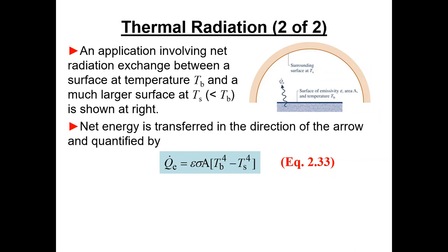They don't have to talk about it, because view factors get complicated. You have to do the three-dimensional geometric integrals in order to figure out what percentage of what one thing sees is something else. So you do some of that. There's charts that we use in heat transfer for different standard geometries, like two planes that are offset a little bit.